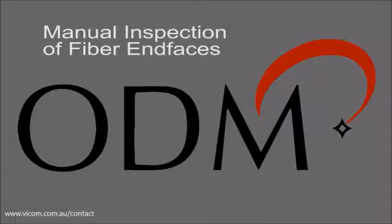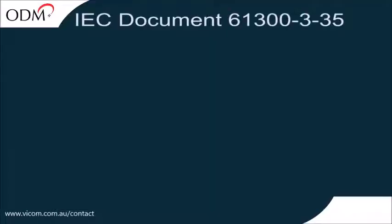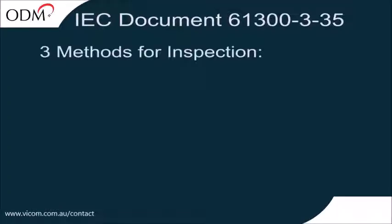This video will explain the manual grading process for fiber end faces using the Inspect software from ODM. According to the IEC's International Fiber Testing Standard Document number 61300-3-35, there are three acceptable methods for performing fiber inspection.